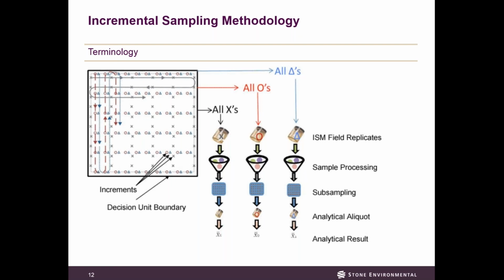And then you run either a mean or you do a UCL, upper confidence limit, through a Chebyshev analysis or one of those to develop your upper confidence level or your mean, depending on your regulator. In Vermont, we use UCL, 95% UCL, as our value from ISM sampling.